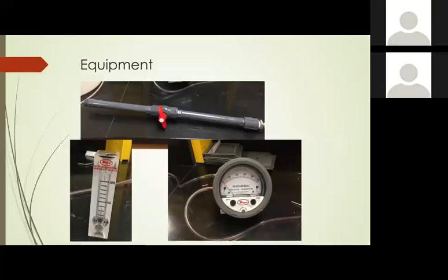And to figure out how much flow we've gotten so that we can get that V squared term, we've got a meter here. Now, there are all kinds of things that students have to do to get this done right. One is the meter is calibrated at sea level. Did they think to calibrate it at Laramie? Because it's got the less dense air running through it now. 3/4 of the students remembered to correct it for Laramie, and 1/3 of those students did it correctly.